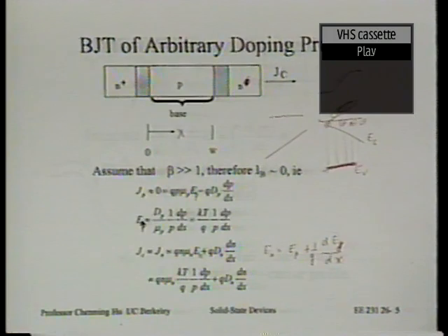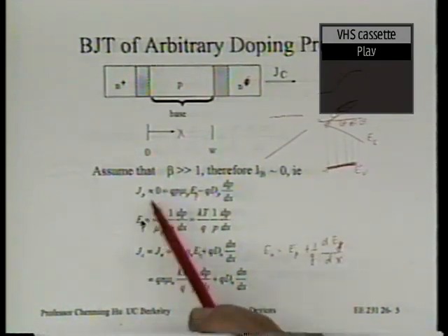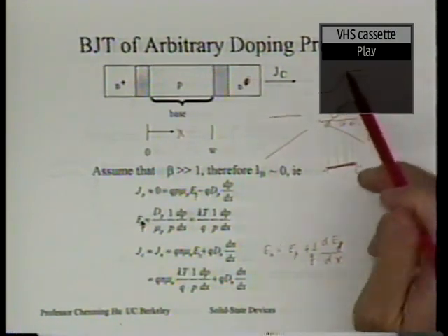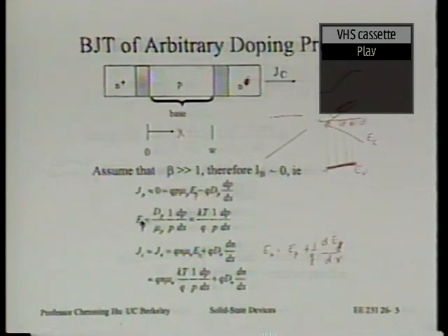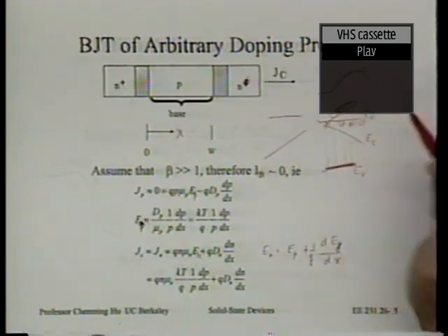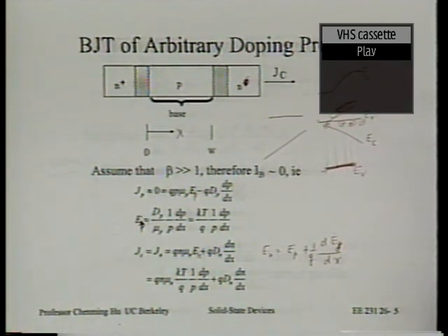All right. So electrons and holes can experience different electric fields in the drift term, and what's responsible for the acceleration of the electrons is the gradient of the potential of electrons, and the potential of electrons is EC. The potential of the holes is EV. To the extent EC and EV are not parallel to each other, electrons and holes will experience different electric fields. Okay. Does this lead to any inconsistency? It doesn't, fortunately.